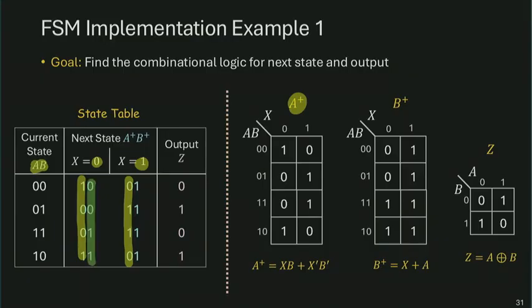All of the B plus columns go to a separate K-map. I'm copying over the column 1001, 0110, 1001, 0110 to the A plus K-map, and the column 0011, 1111, 0011, 1111 to the B plus K-map.